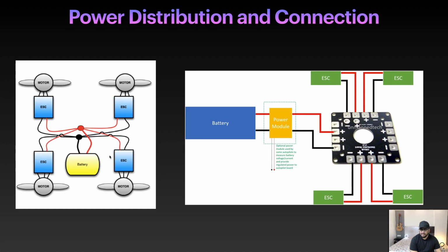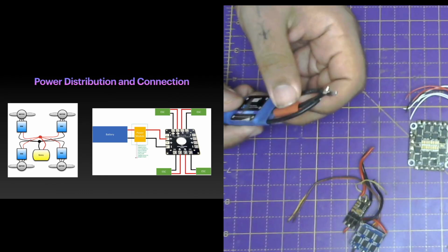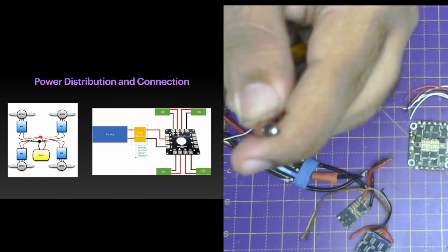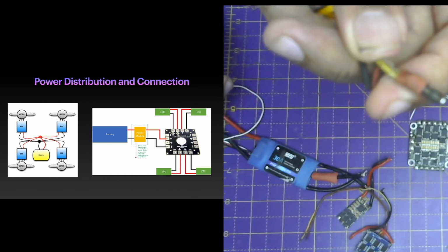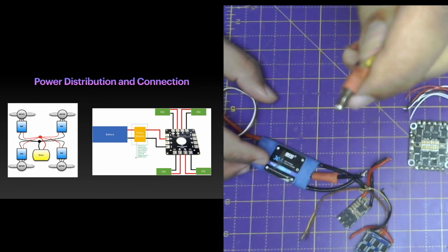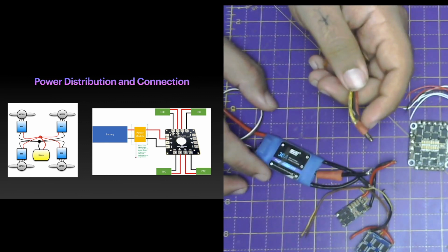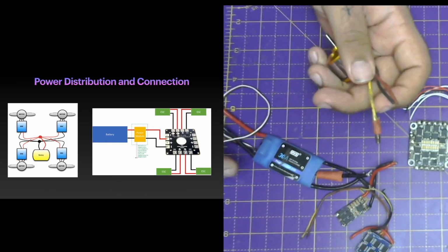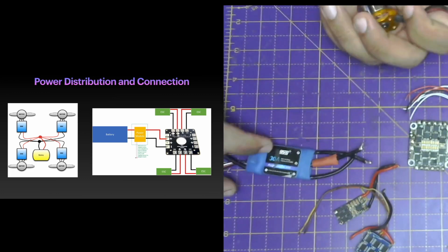Yes, so there are different ways to connect your motor to your ESC. One way is something called bullet connectors, like this. So these are the bullet connectors. You can connect these bullet connectors to your ESC bullet connectors. But as I mentioned in the first chapter, every gram counts in case of a drone, and every gram adds to the weight. So nowadays what people do is